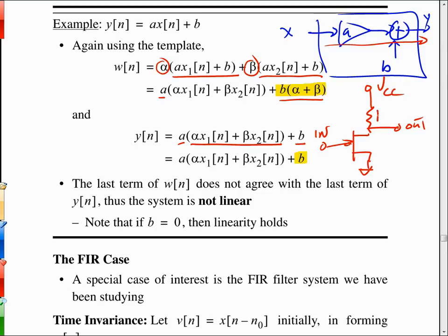So if this was a resistor right here, called the load resistor on an amplifier, and there's some biasing in here, and the upside down triangle means tying it to ground, there's going to be a DC bias added onto this output because there's going to be some current flowing down through here, which is going to put a steady bias voltage on there.